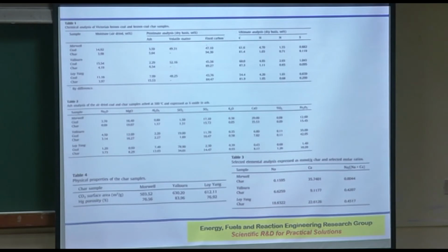The way mercury porosimetry works is that if you want to measure the porosity of a material, the standard is that you force high pressure mercury into it, and whatever amount of mercury you have been able to force in represents the volume of the pores. Instead of mercury, it could be anything else which was stable, but in this case mercury is the choice. That's the universally accepted standard for measuring porosimetry.